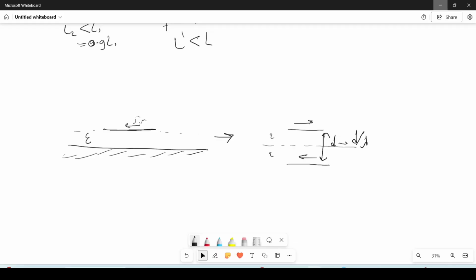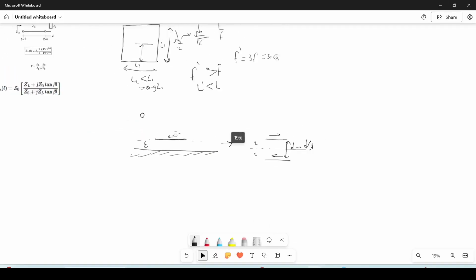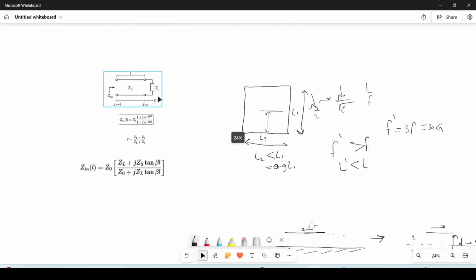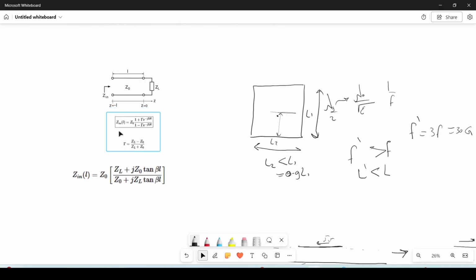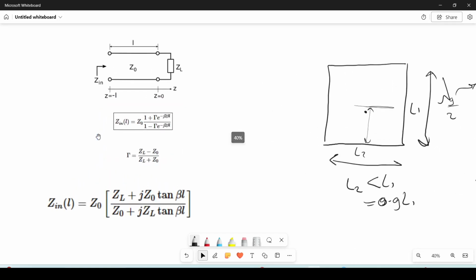And then if you remember, when I have an impedance and a transmission line, I have the input impedance, which is basically changing because our antenna here is like XL plus RL, so it has real and imaginary parts. So this gamma is complex, which means this N is also complex.